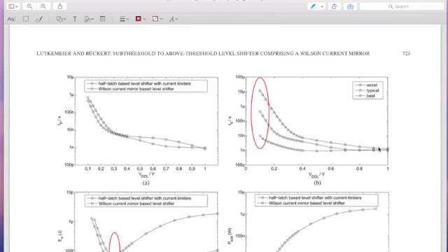Here is another interesting thing to see, is that they have characterized the delay of their level converter across voltages for 3 different process conditions. And you see at these low voltages how much spread there is. And you see this is actually a log plot. You can be orders of magnitude away. Right? So that is one of the challenges of very low voltage design, is that the process variability will lead to very large performance changes. So that is something one has to work with, or have a way of addressing.